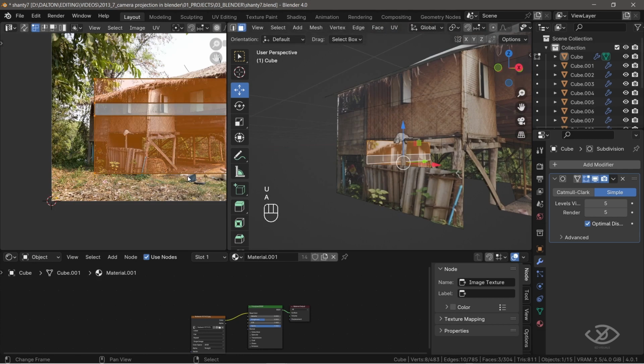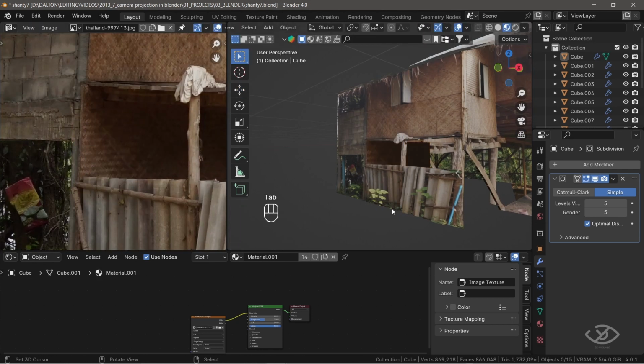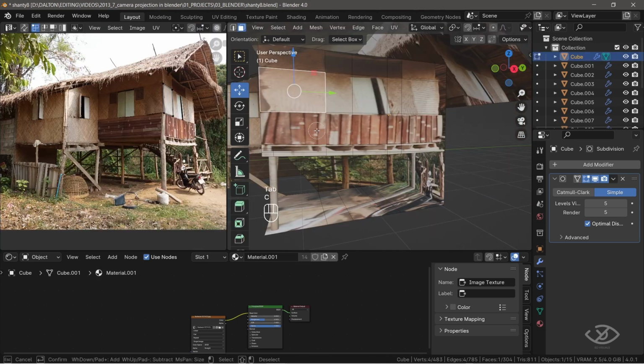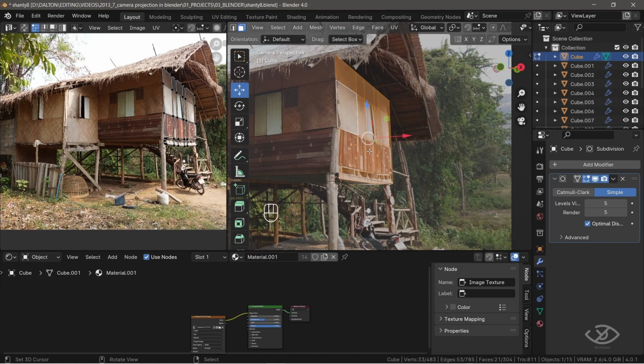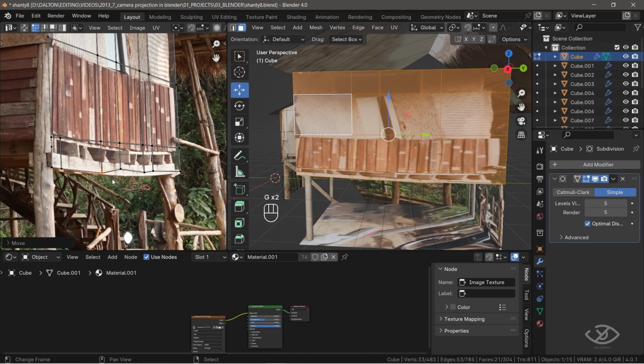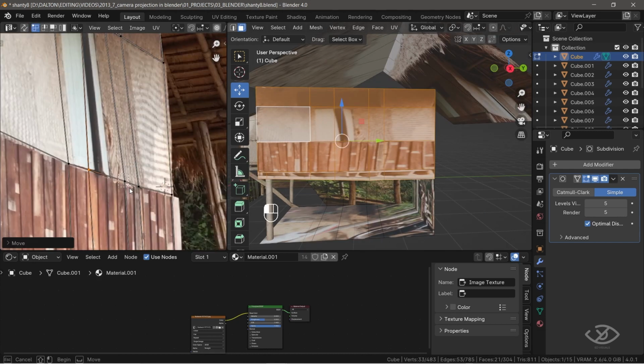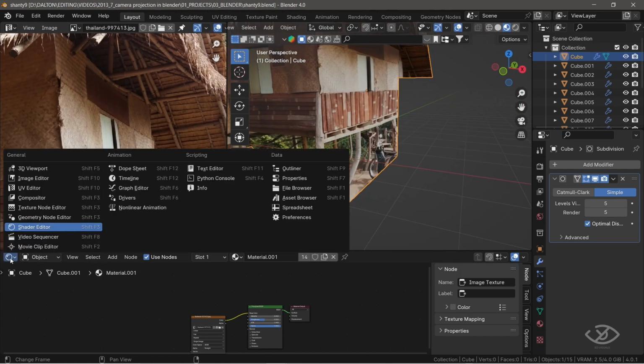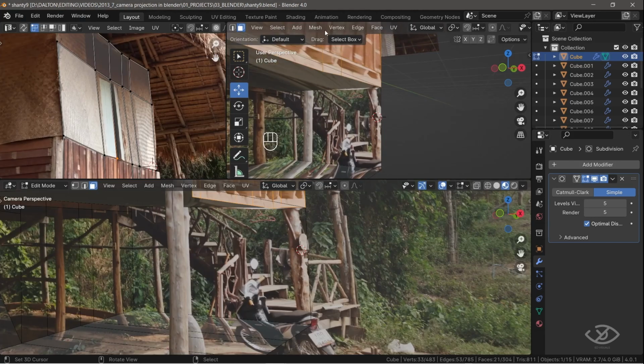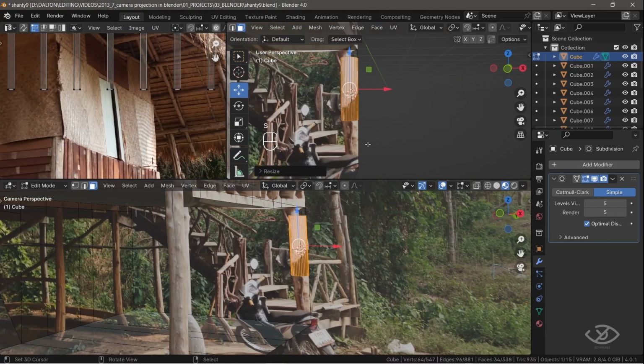Cube projection. Place the edge loops over the reference image to match the textures. On Edit mode, select this facade by pressing C, Project from View, then align it to the reference to match the texture.